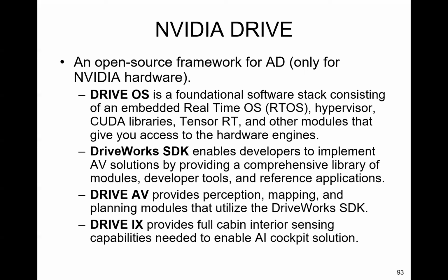DriveOS is a foundational framework consisting of a real-time operating system, hypervisor, CUDA libraries, TensorRT, which is a TensorFlow library, and other modules. DriveWorks SDK provides a comprehensive library of modules. DriveAV provides perception, mapping, and planning modules. And DriveIX provides cabin interior sensing, for example, monitoring the driver.